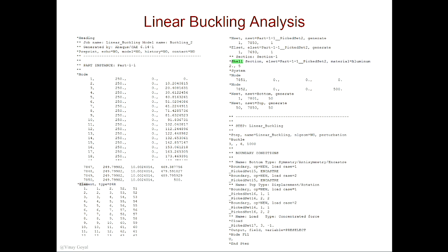Okay, so let's think about that for a second. Why is that? If I apply pressure, what's happening to that wall? It's in tension, yes: PR over T and PR over 2T. So that wall is in tension. Now I apply compression loading. Isn't that counteracting the fact that I have pressure inside? That's why you have this pressure stiffening effect, which helps the structure not buckle as soon as if it had no pressure. This can be quickly included in this model, and it's not very hard to do. Perhaps if we have time we'll demonstrate that. If not, that's fine. We can talk about it after class.